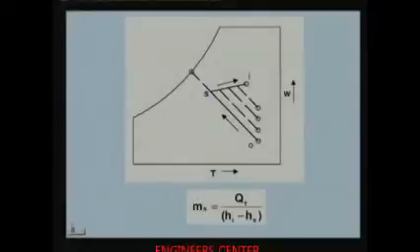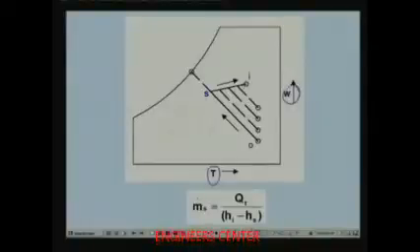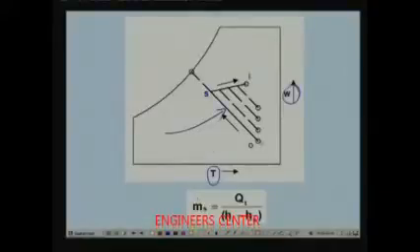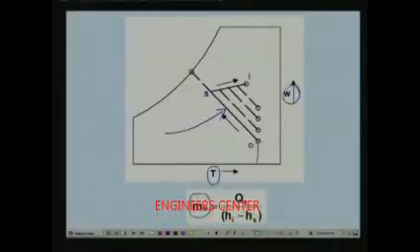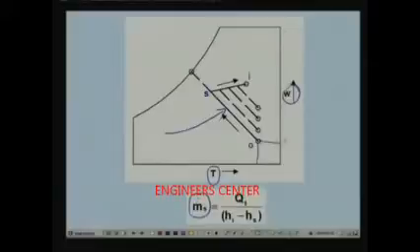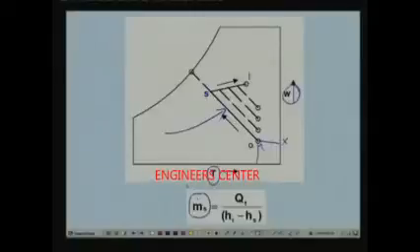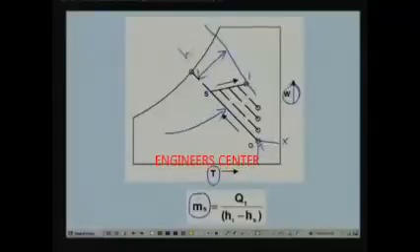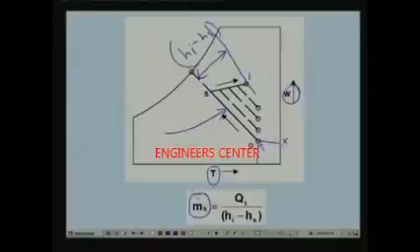This is again what I have shown earlier, a psychrometric chart. You have the dry bulb temperature and humidity ratio, and this is the cooling and humidification process that takes place in an evaporative cooler. O is the inlet condition and S is the supply condition, and we have seen from the energy balance that the required air flow rate m dot s is Qt divided by (Hi minus Hs). Let us say this is your inlet condition, which is the condition of the outdoor air. Then Hi minus Hs, if you draw a constant enthalpy line, is this. So you can see that the required mass flow rate is inversely proportional to this enthalpy difference.